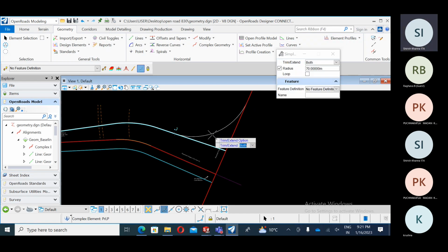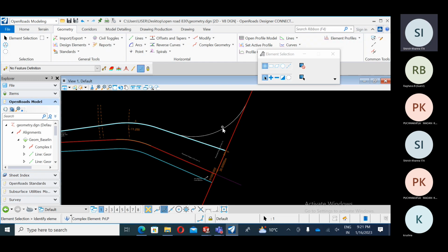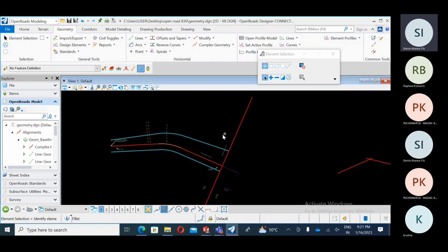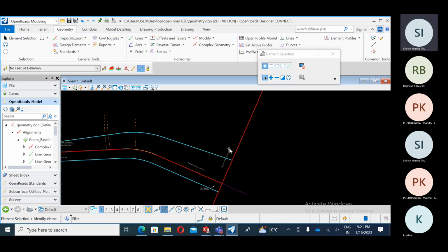Oh, one second. One portion is left here because we are creating between the pavement and the master center line. No, I don't need to create it here. We had to create one more offset value first, like 11, and then we need to create that. Okay, because we had to create the same type of edges when we applied the fillet.